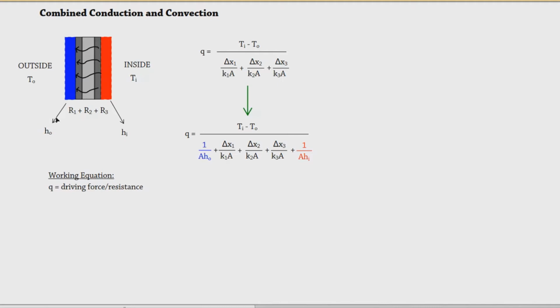So this is dependent on the temperature and the fluid that is inside and outside. For example, the outside fluid is simply air, and the inside fluid would be, for example, a hot oil. So we will be using the heat transfer coefficient for oil, and then the heat transfer coefficient for air for the outside. Now I want you to look at this A.